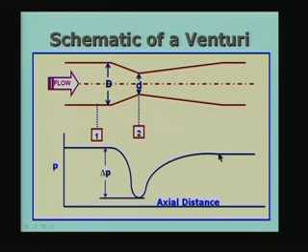But you will see that the pressure here is slightly different from the pressure here, because the pressure does not come back to the original value, but there is a slight difference between P1 and the pressure at the exit. This difference is called the irrecoverable pressure loss, and later we will see how it varies with different flow metering devices: the venturi, the nozzle and the orifice plate.